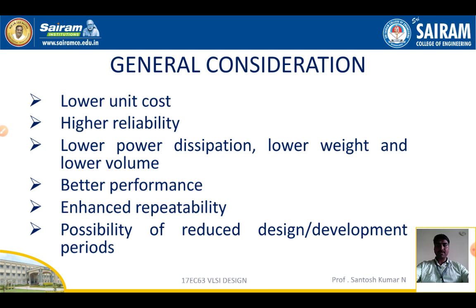General consideration. Before going into general consideration to be made for designing, let us know what is a subsystem. A subsystem is a small unit block of a complex block. For example, let's consider a full adder as a complex block. We know a full adder can be constructed using two half adders. Therefore, a half adder acts as a sub-block through which a complex block, that is a full adder, can be built.